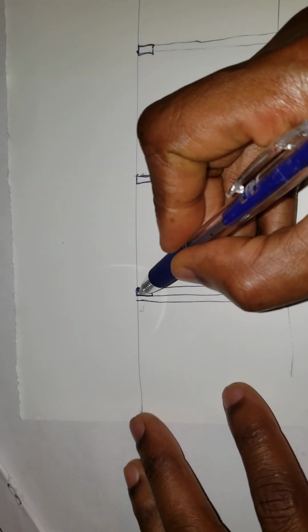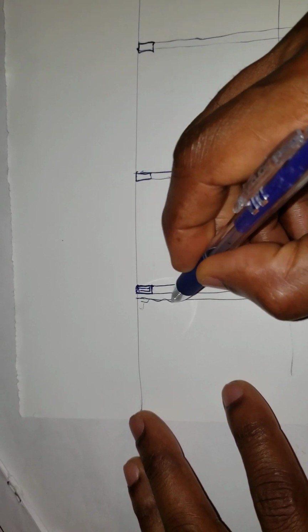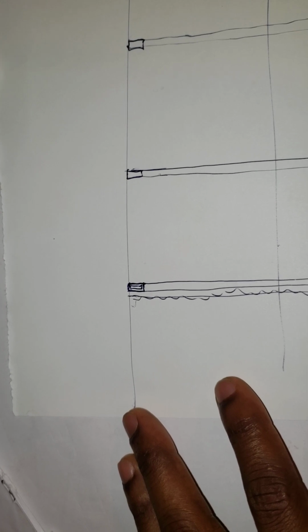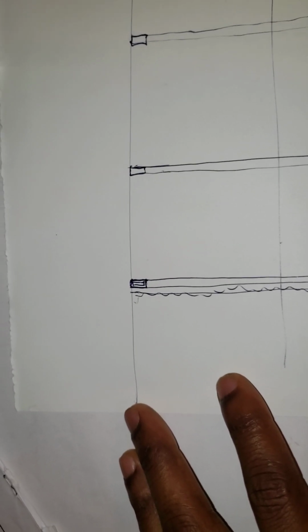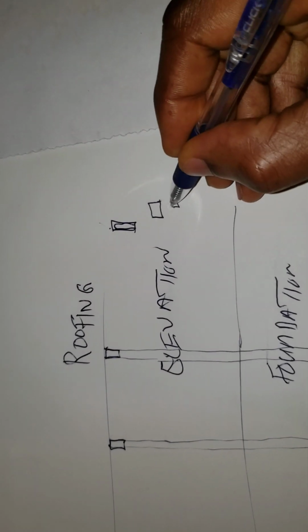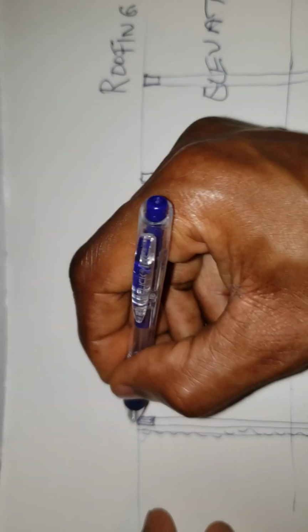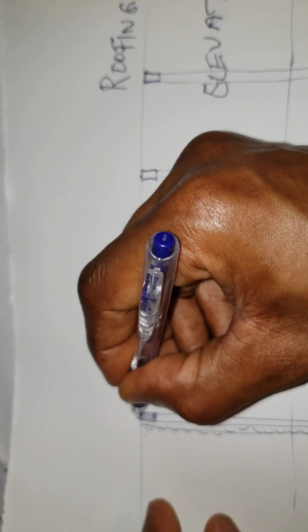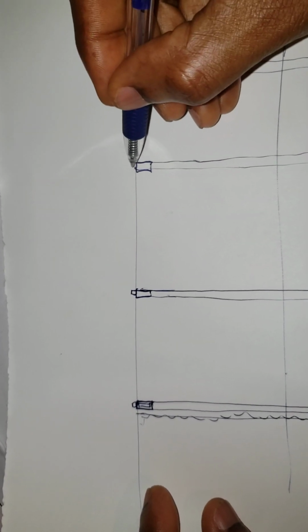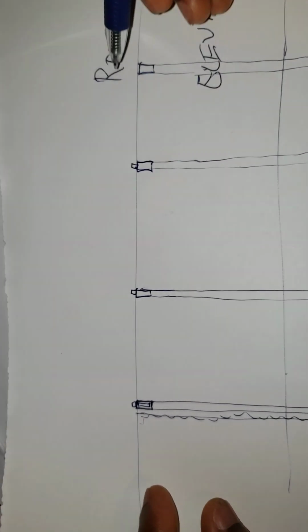Next, we would need our wall plate. Wall plate is typically 100 by 75 or 80. So we will draw our wall plate, copy and paste it into these locations. One wall plate there. Next wall plate there.